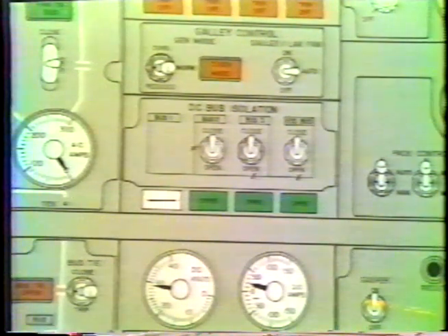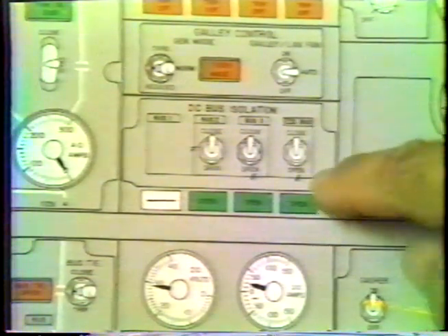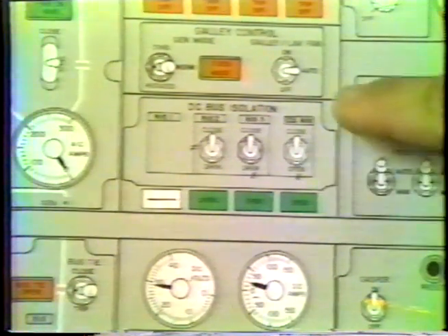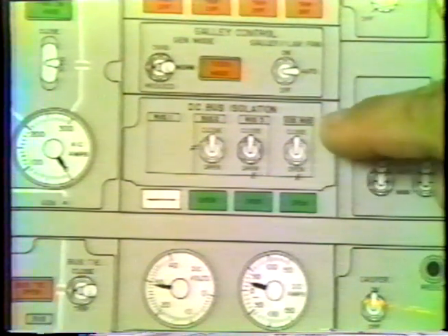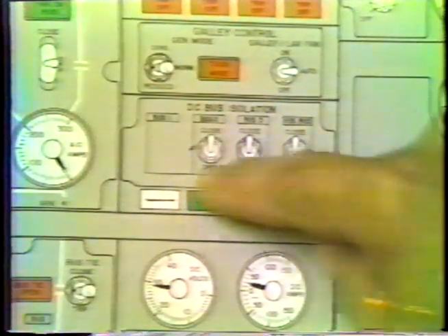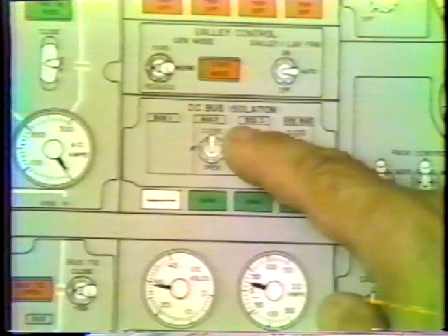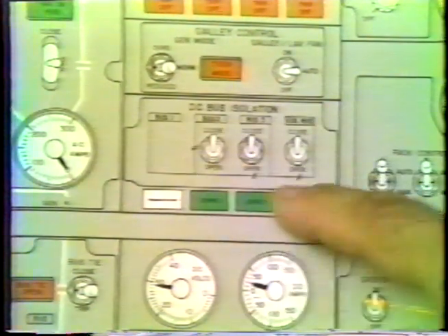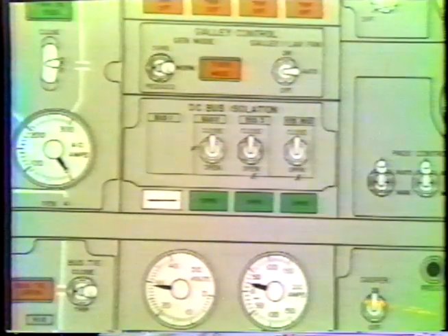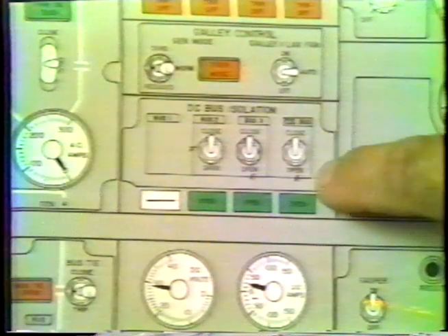The one exception to that is on some aircraft, the Essential bus has a blocking diode that will make the Essential bus available only for the Essential DC bus and not for the other DC buses. However, any one of the DC buses 1, 2, or 3 can and will feed the Essential DC bus, but not backwards. On some aircraft, this blocking diode has been removed.